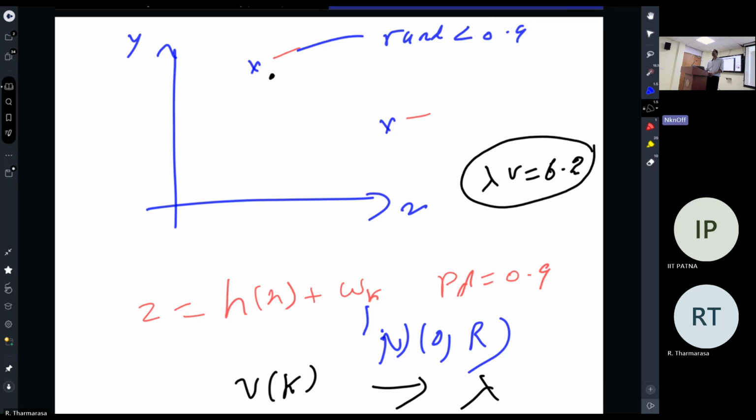This says that on average you will get 6.2 detections as false alarms. Then you generate a Poisson random number from that. So that says, okay, 10. You are going to generate 10 false alarms uniformly in the whole region. The whole region is like that, and you generate uniformly 10 detections somewhere here.